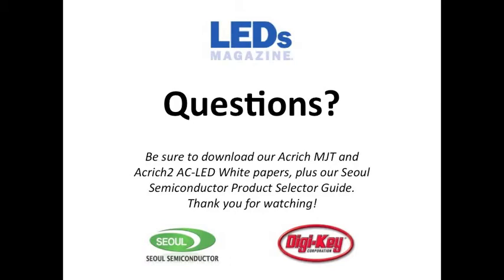Yeah. So good question. There's a lot of different drivers out there today, a lot of different technologies. Do you want to design your own driver? Do you want to go out and buy a brick from somebody or a power supply from somebody else that's already done? There's a lot of different technologies to it. The manufacturers of the actual discrete regulators, DC switchers, have gotten a lot easier. There are a lot more app notes on them, so it makes it easier for customers to design them on their own. With typical conventional drivers or power supplies out there, though, you're going to have an inductor, you're going to have electrolytic capacitors, you're going to have your switching regulator in there.